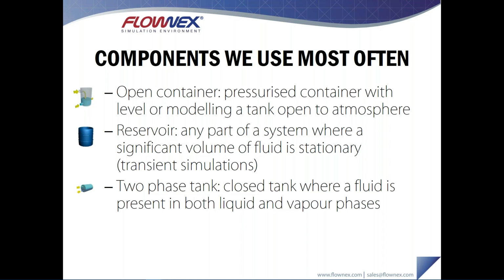So perhaps you have a simple HVAC simulation, and you're trying to simulate the flow into a room. The air inside of that room has quite a significant volume, and in a transient simulation, that volume can have a large effect on your results. So modeling that volume with a reservoir would be an ideal way of capturing that inertia. All of the accumulation terms would basically capture that effect.